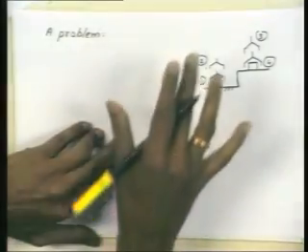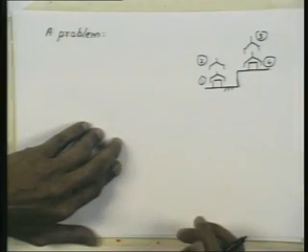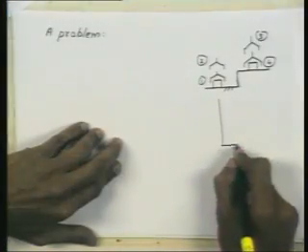Right? When we give these specifications, in order to make the robot move from position 1 to 2 to 3 to 4, we need to calculate what would be the joint angles or joint positions, so that we can control motors in order to make the joints follow those variations of joint angles with respect to time. This is what you learned as joint interpolation, right? So in joint interpolation,